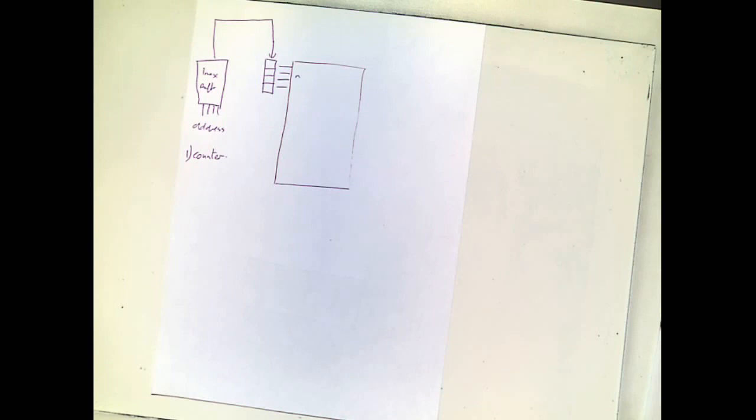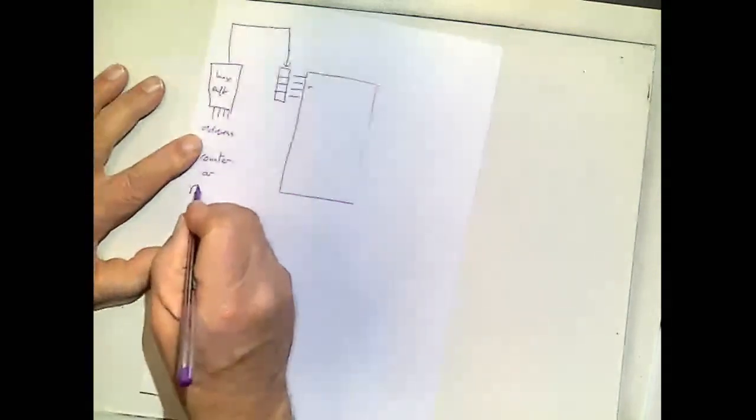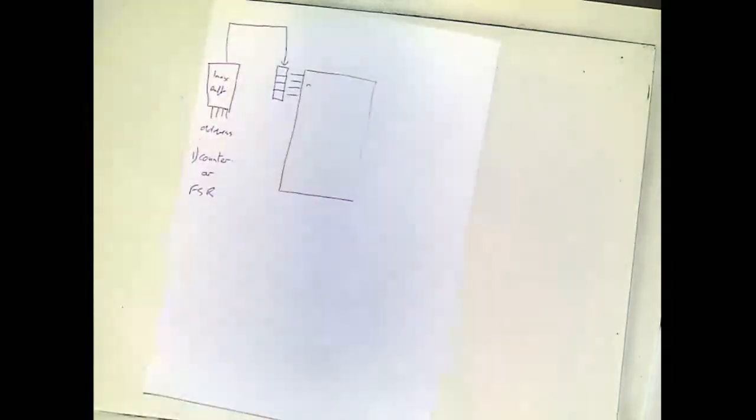Yeah, what is that? Feedback shift registers. So that could be a feedback shift register. Oh, you haven't forgotten those wonderful devices, generating millions of numbers from just giving a starting state of a buffer and a feedback function. And send them to Australia, and they can generate the same set of numbers. Fantastic. If I wanted a particular optimized mapping, remember feedback shift registers will generate random or pseudo-random numbers. If I wanted a fixed number, I would need to store the numbers in the memory.